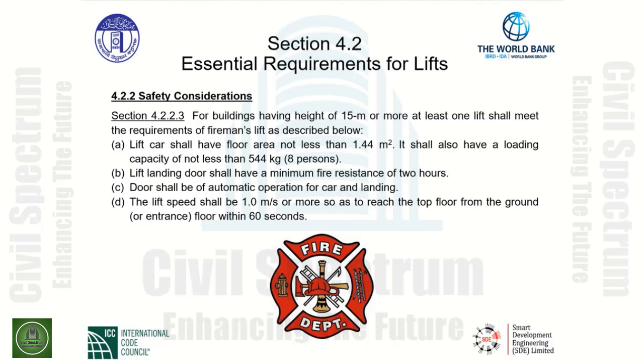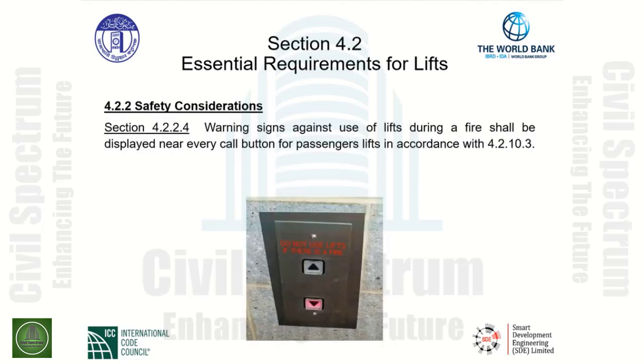B. Lift landing door shall have a minimum fire resistance of 2 hours. Item C. Door shall be of automatic operation for car and landing. And finally, item D. The lift speed shall be 1 meter per second or more so as to reach the top floor from the ground within 60 seconds. Again, these are specific requirements for the fireman's lift.